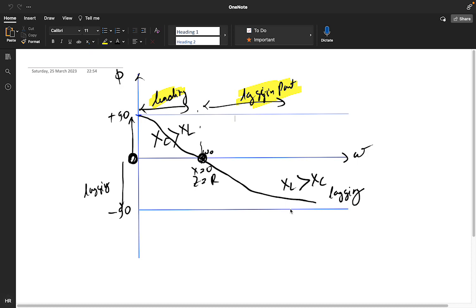And you have to say when your voltage source and current source are in phase. It's a very simple definition of resonance. When the voltage phase and the current phase are in phase, that circuit is known as resonance. In that circuit, there should be a resistor, an inductor, and a capacitor. The inductor and capacitor cancel each other, and you get the frequency value 1 upon 2 pi root under LC. It is in hertz, and if anyone asks in radians, then omega is equal to 1 upon root under LC.